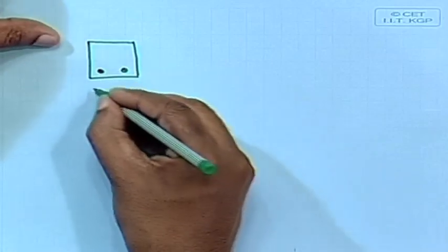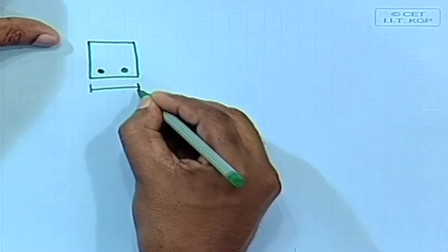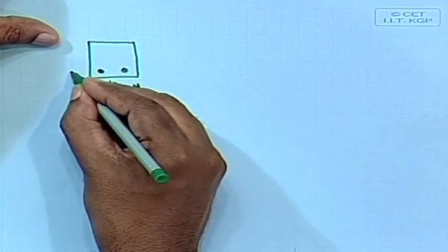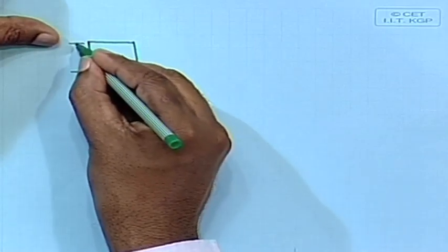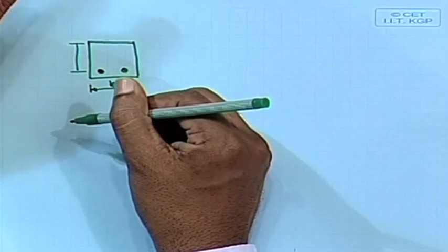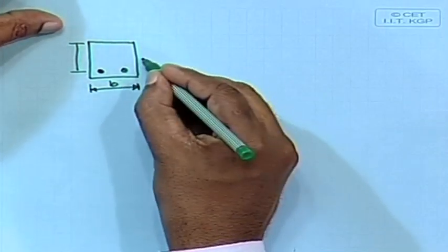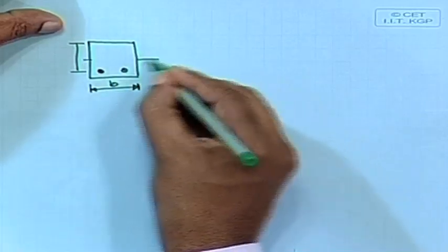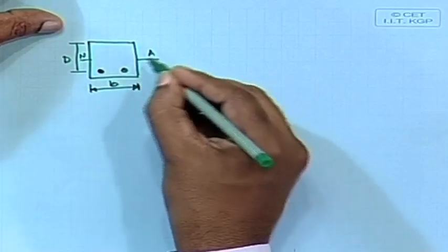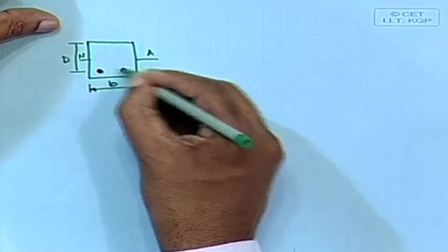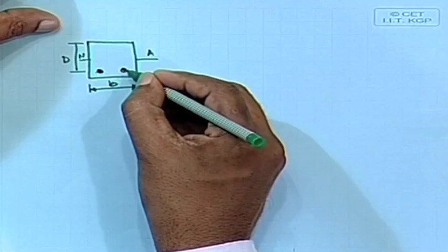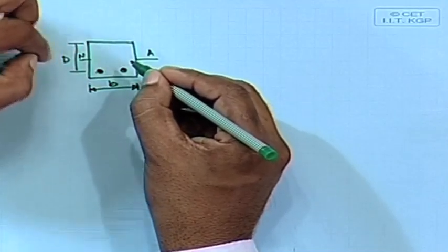So, this is the concrete section, and here we are assuming that concrete in the tensile part beyond the neutral axis, and definitely there should be a neutral axis, will not take any load. So, it will be resisted by these two bars only for this particular example.